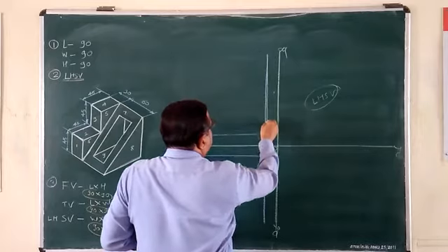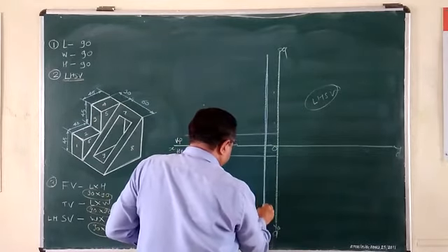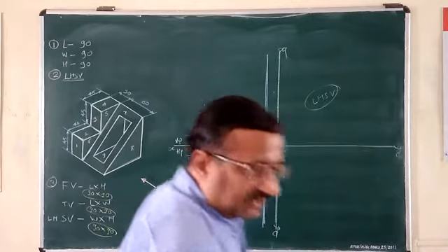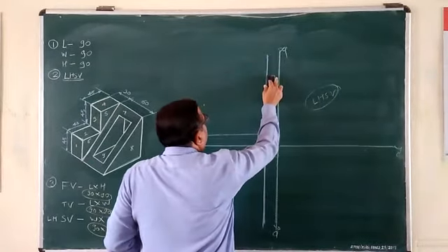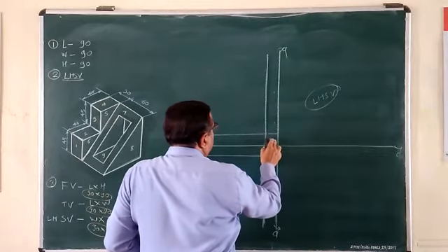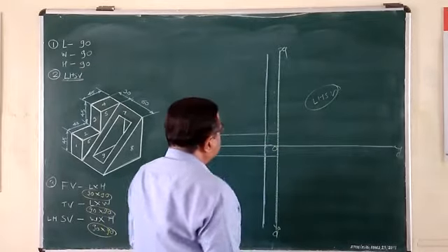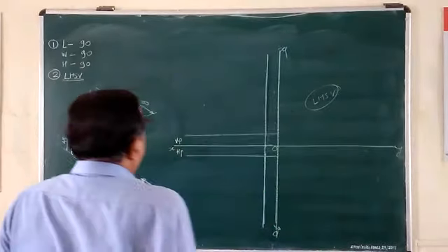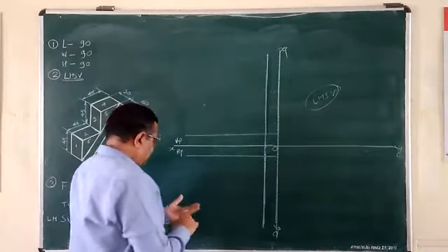For proper spacing of the front view and top view, we are carrying out this activity. This is its significance. The proper look of those views can be expressed by this spacing method. The same space is maintained above, below, and on the left side.